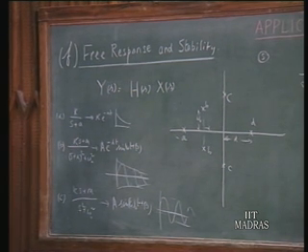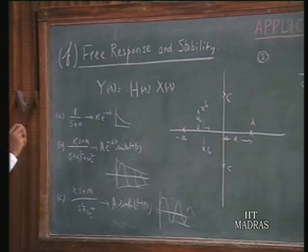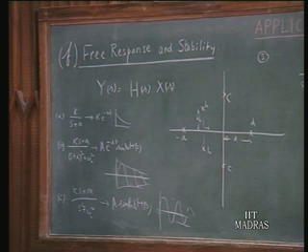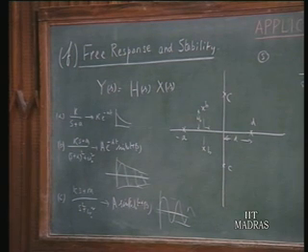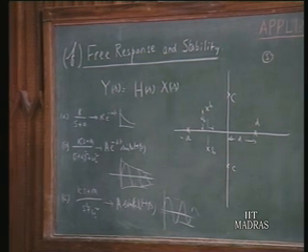If the system is stable, a bounded input must give rise to a bounded response, and so the response cannot take off to infinite limits. It can't grow indefinitely with time, and the requirement therefore is that the poles should be in the left half plane. If on the imaginary axis, they should be simple.